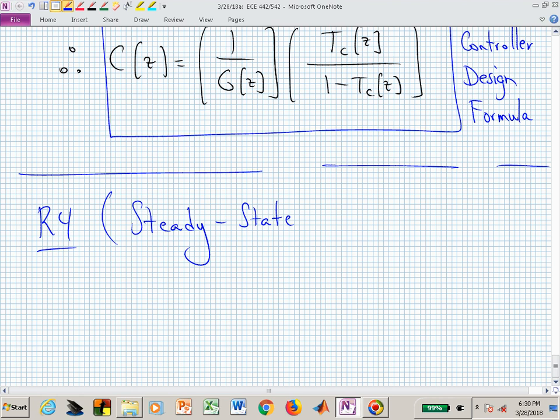That's my steady state accuracy after the transients have all disappeared. And how long does it take for the transients to disappear? 5 time constants in continuous time. Here it's so many sample periods, isn't it? And that's our definition of infinity, really. So now, when is infinity a small value? In this controls class, you could go to infinity in time by taking r to the n equal to 0.01.